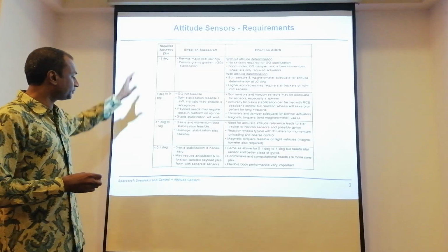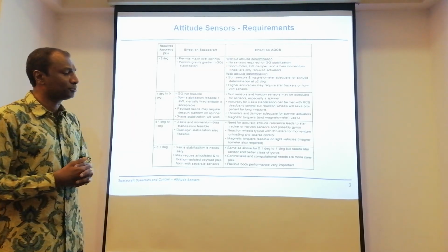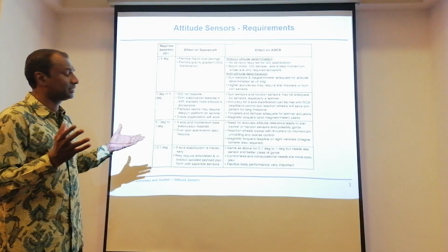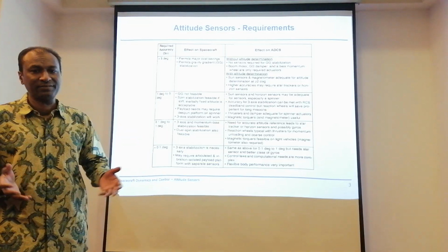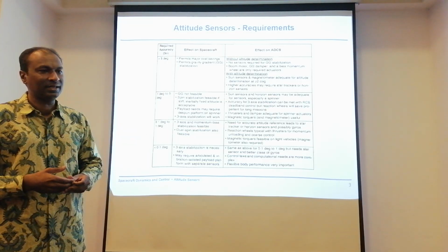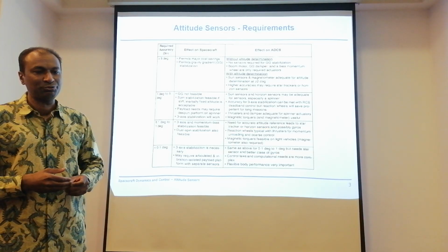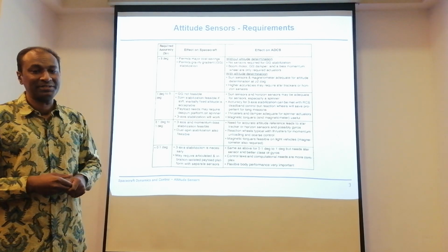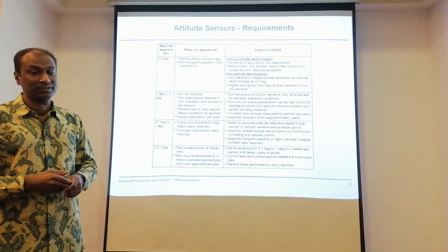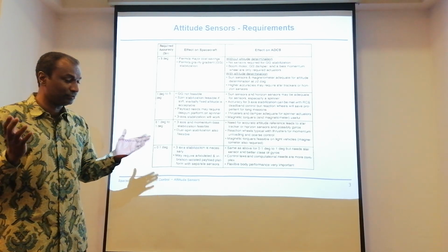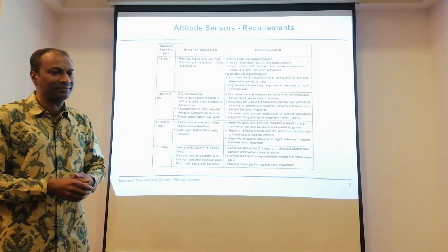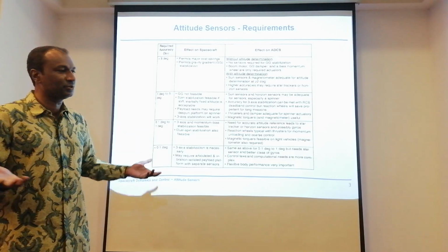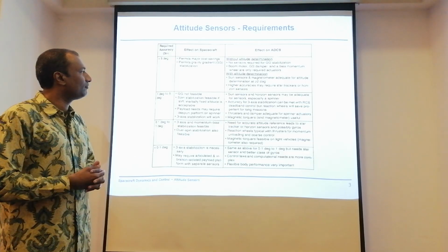When you look at all these options that we have, in terms of effect on the spacecraft, the most primitive way is a gravity gradient stabilized satellite. You cannot expect much attitude accuracy, not better than 5 degrees. Technically, it's a passive way of stabilization, which means that you don't depend on any sensors. There's even no point in having sensors, because you can't control it. So it's like a free fall, as you can see.